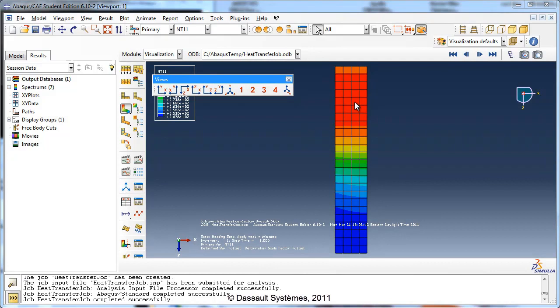The upper half, with a constant surface temperature of 400 degrees Celsius and a heat flux of 5,000 watts per meter squared, is colored red, indicating high temperatures, whereas the lower half is blue due to the lower constant wall temperature of 350 degrees Celsius and heat loss by convection and radiation from this region. The contours gradually pass from red to blue from end to end.